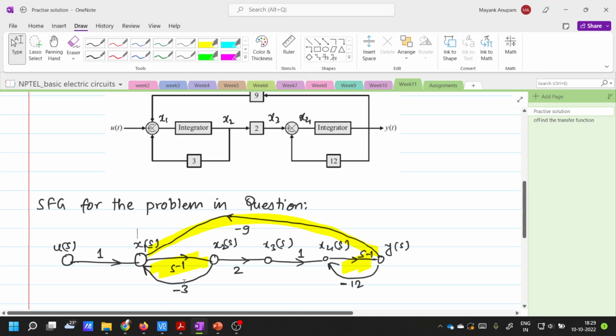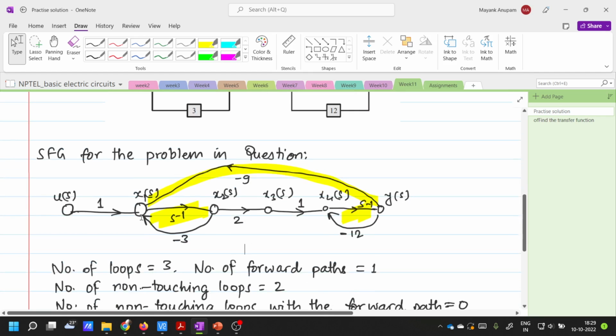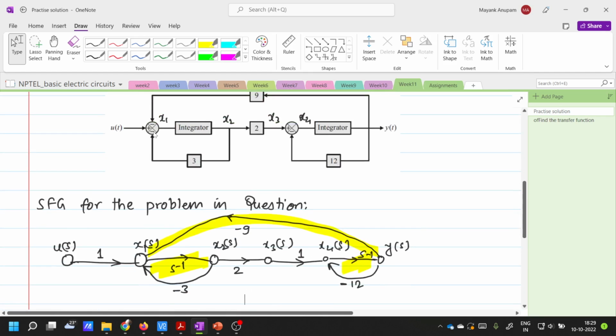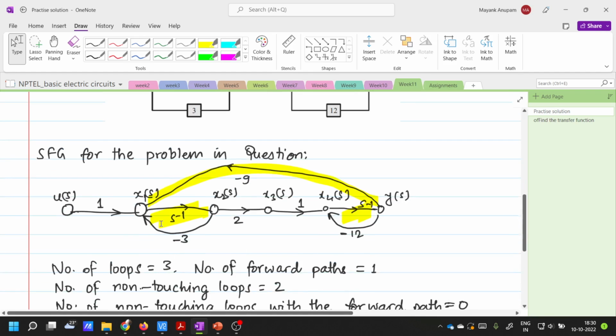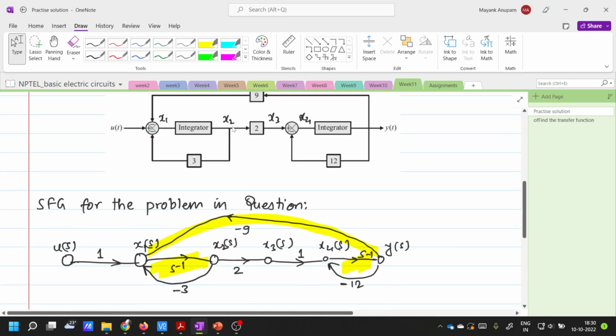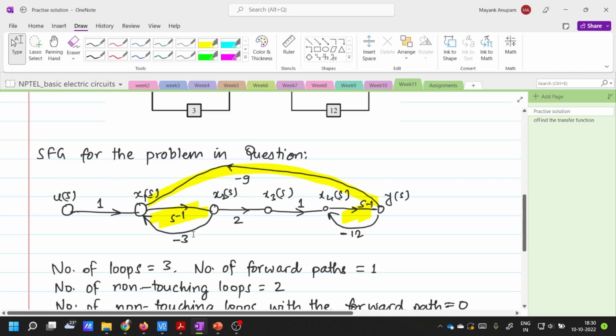So you have to multiply it by -3 because in signal flow graphs you do not show any plus or minus sign in the addition or subtraction at the node. You just make an arrow to the node. All the arrows that are converging to a node are simply added, okay? So if you want to subtract a particular signal, then you have to multiply a -1 to the transfer function here.